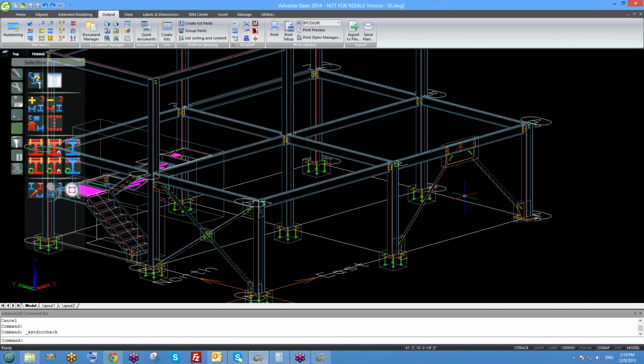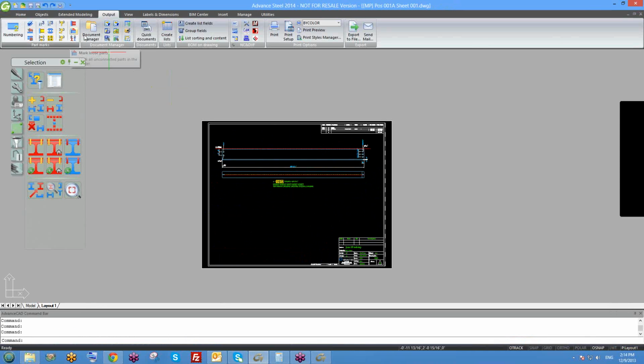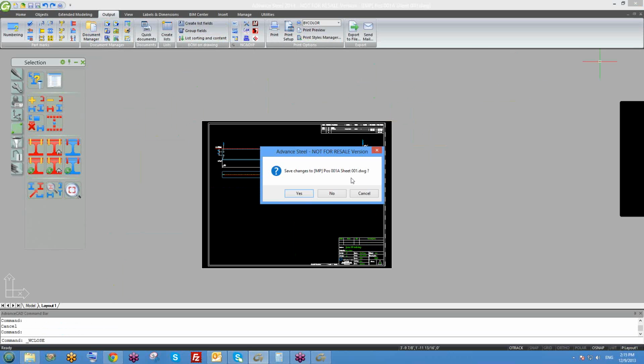Okay, so you went to Document Manager and then, yes, or was that just it? Just Document Manager right there? Right there. But this Document Manager only works if you are on the model space. If I click here, nothing happens. Take a look. This command only applies to model. So you cannot open up your drawings if you are under your drawings.